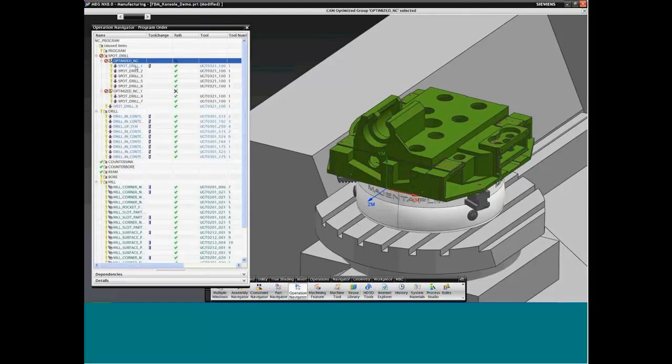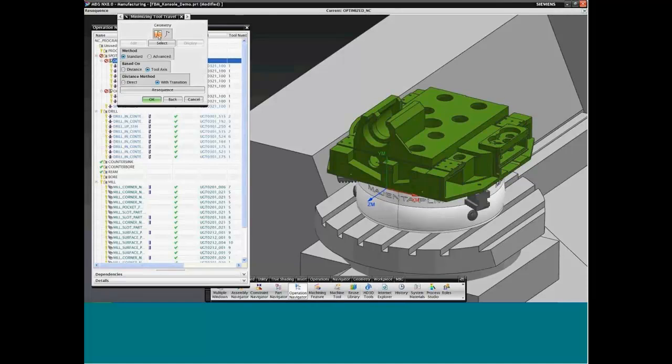What we can also do is, if we then double click on that optimized group, we can optimize it even further by minimizing tool travel, or we can actually machine the holes in bands, so we can go vertical or horizontal. If we say minimize tool travel and hit the edit parameters button, you can see that we can select a start hole.